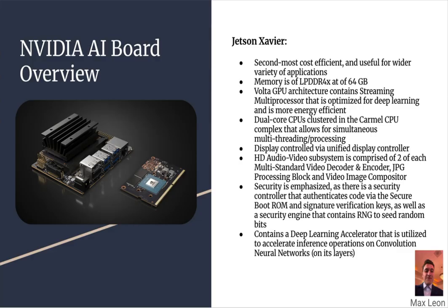Also, security is emphasized as there is a security controller that allows for the authentication of code via secure boot ROM and signature verification keys, as well as a security engine that contains RNG to seed random bits. And it also contains a deep learning accelerator that is utilized to accelerate inference operations on convolution neural networks, which essentially speeds up AI tasks without taxing the GPU or CPU resources.